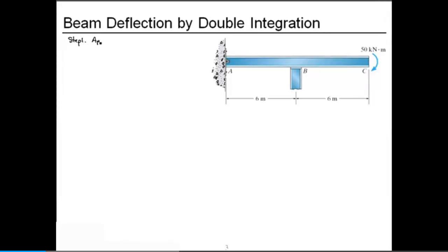Step 1, let's approximate the answer. If we look at the deflected shape of this beam, we expect it to be something like that. Well, we can approximate this situation and look at just the cantilevered end with the couple moment, and we get a downward deflection as such. Now, since the region from A to B can deflect, that means we get a rotation at B. So this vertical deflection we expect to be larger than this, but this will put us into the ballpark.